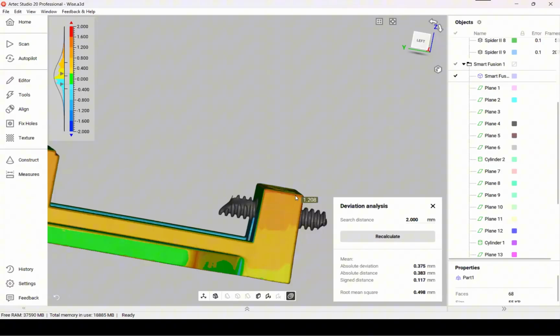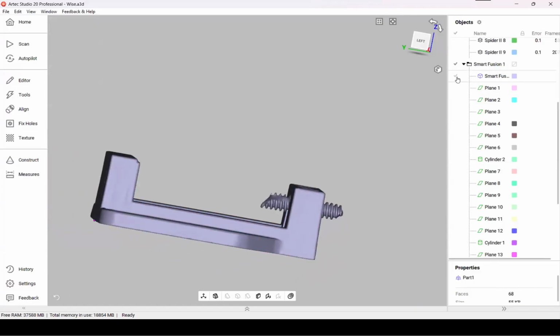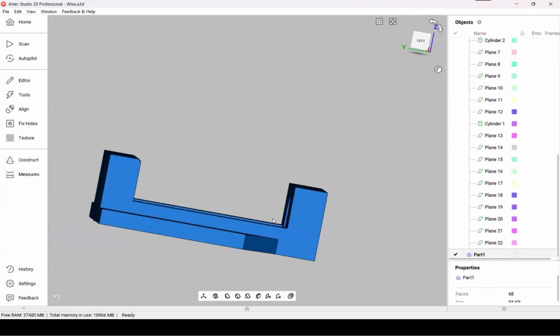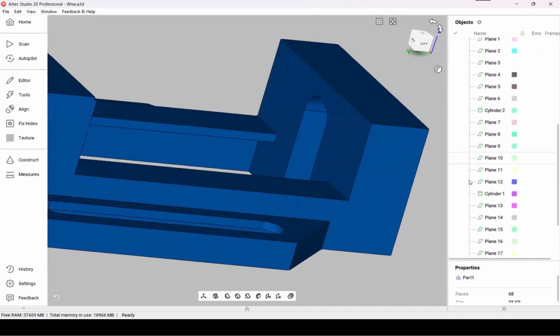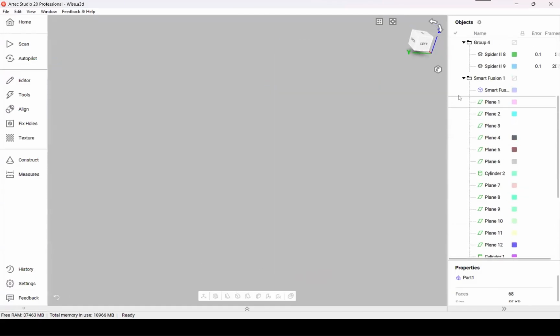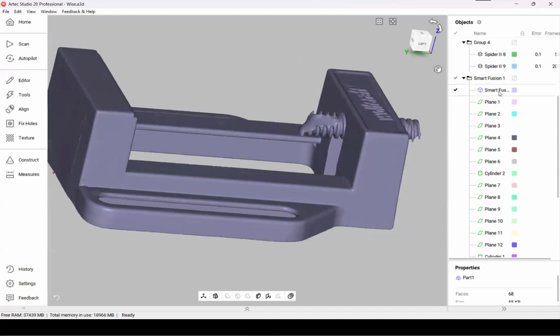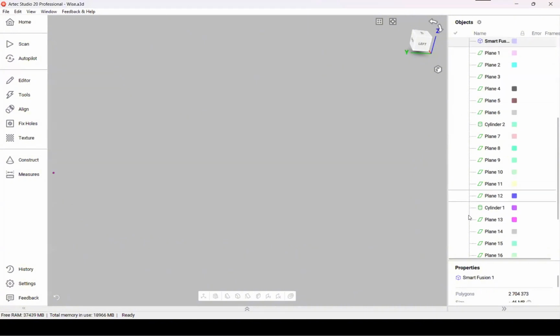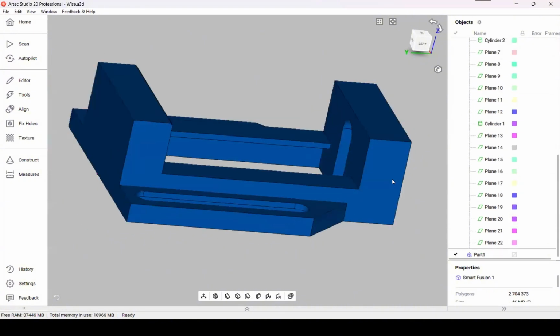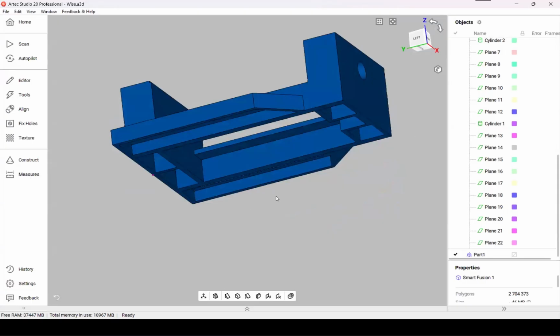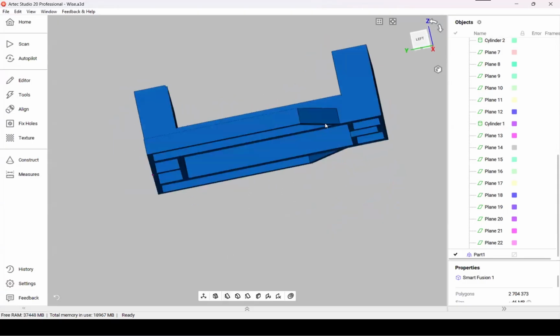Of course, you can do all the final touches in the SolidWorks interface, but we have some tools here, and I will show them to you. Here's my part, and you can see that if I check the mesh, some parts are not accessible, but if I mark CAD, all the tools are accessible.